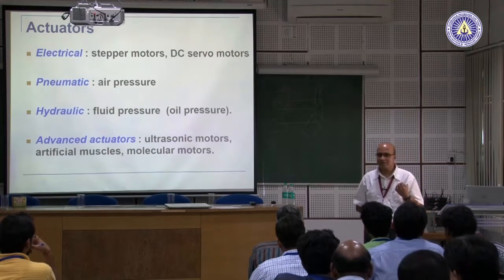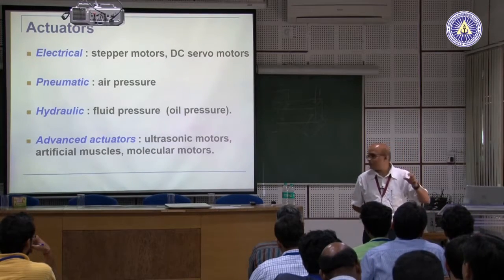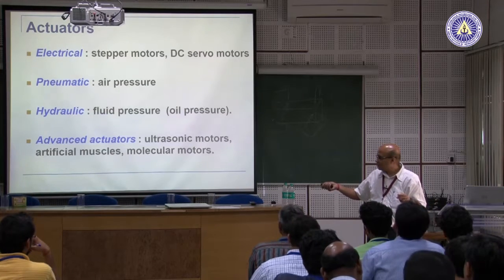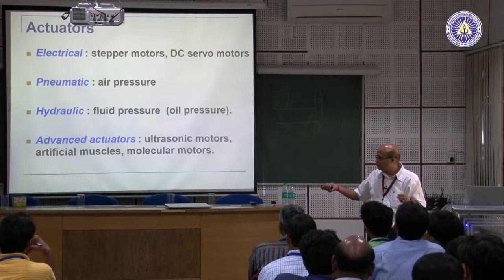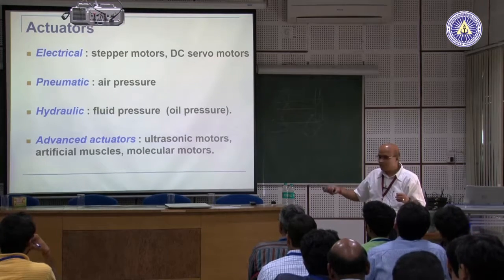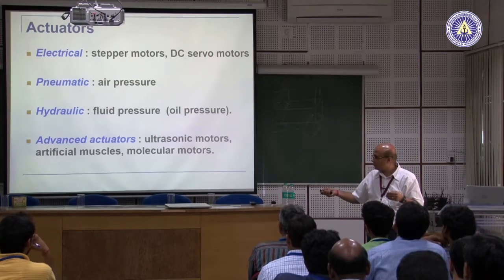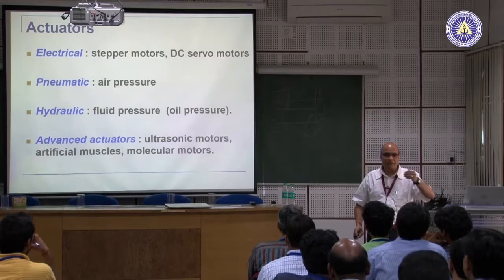Pneumatic is safer. When you have a gripper, the structure is like this: there is a motor, there is a gear in front, and there is an encoder at the back. If this is a gripper finger and it is moving, suppose it hits something. It will not go backwards, because there is a gearbox there. You cannot drive it back.